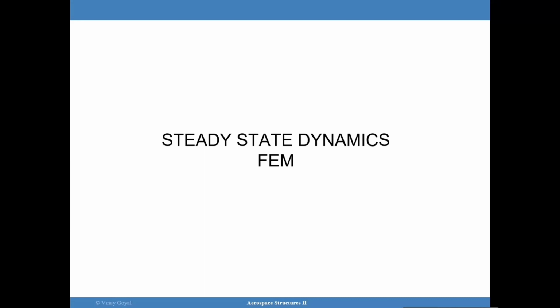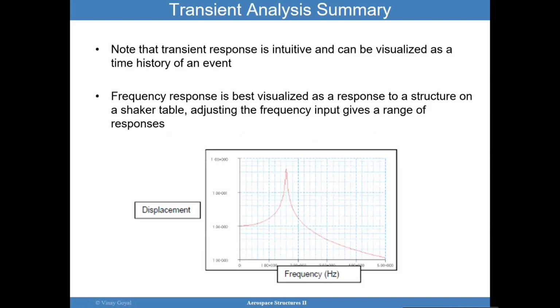So we're going to dive into steady state dynamics using finite elements. We already discussed steady state dynamics earlier, but I want to cover how this would be done in finite elements. If you recall, modeling the transient response is quite intuitive. You can see the time history of the event, but there is an advantage to understanding the system's behavior when you subject it to a forcing frequency, and we look at it from the frequency domain. We try to understand what the peak response is due to that input that we put into the system.